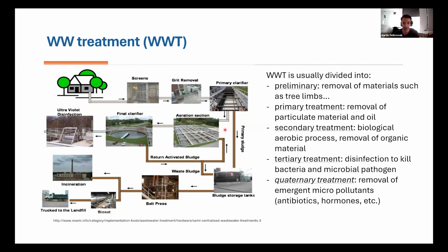Sludge that comes from the clarifiers is settled. This sludge is called waste-activated sludge, and it usually goes through anaerobic digestion in the absence of oxygen, where anaerobic bacteria digest it and produce biogas. With this process, the volume of the sludge is reduced and some energy is recovered.